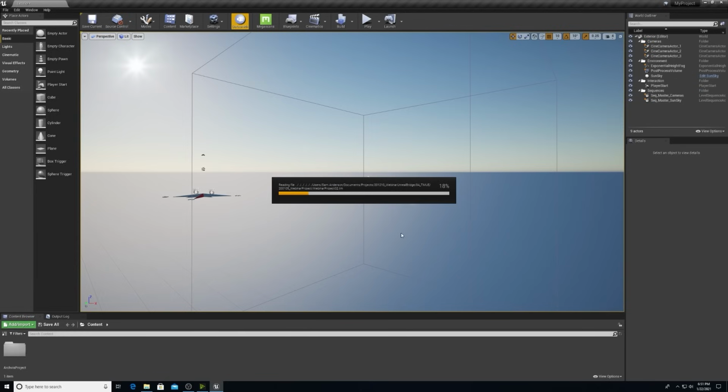Now, as I mentioned, we are going to be showcasing ray tracing, which will give the project a more natural look. It's going to produce soft shadows and accurate ambient occlusion. It's also going to give us interactive reflections, which can be very important in representing materials in architecture. If you do not have a graphics card that supports ray tracing, or if performance is a very important part of your project for virtual reality, you can start the template without ray tracing enabled and continue by baking your lighting.